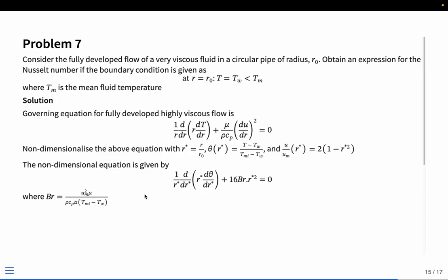If you observe the equation, we have actually neglected the advection term here. Basically, this means we are assuming that temperature variation along the x direction is neglected and axial conduction is neglected. This is true only when you have an isothermal wall that is very long, because in the isothermal case, we know that under fully developed conditions the temperature will vary exponentially and eventually become equal to the wall temperature. So only when you are very far into the fully developed condition, you can assume that this particular term, del T del x, is close to zero compared to the other terms.